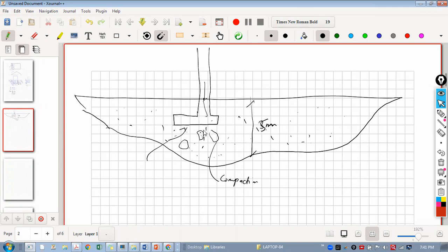In this case, generally, if the strata is quite below, we give the suggestion to go for piles instead of isolated footings. Or if you are doing the isolated footing, you must make sure that it is compacted properly. On the site, the contractor has to take care of the compactions.